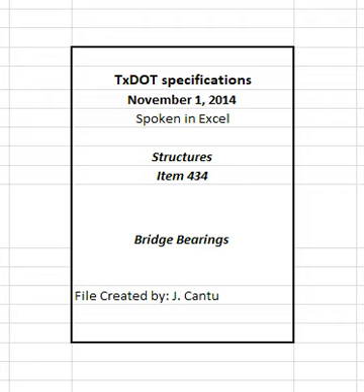HLMR bearings will be measured by each bearing in a specified load range. 5. Payment. 5.1 Plain and laminated elastomeric bearings. Plain and laminated elastomeric bearings used with precast prestressed concrete or rolled steel members will not be paid for directly but will be subsidiary to the pertinent items.